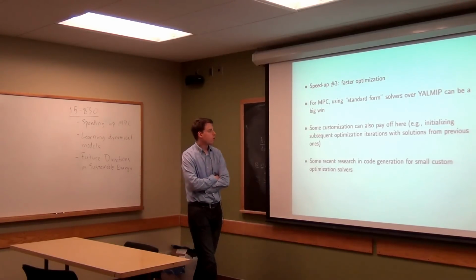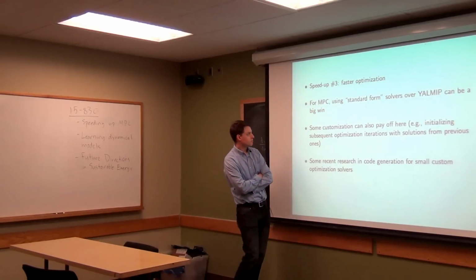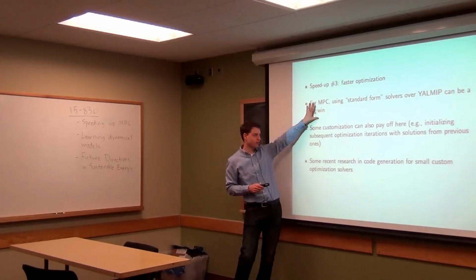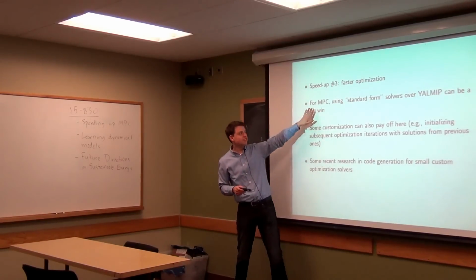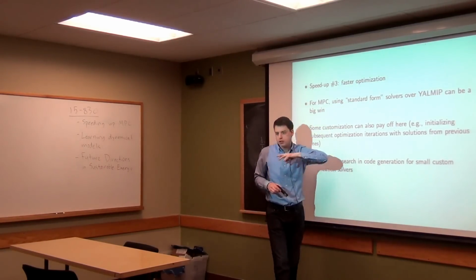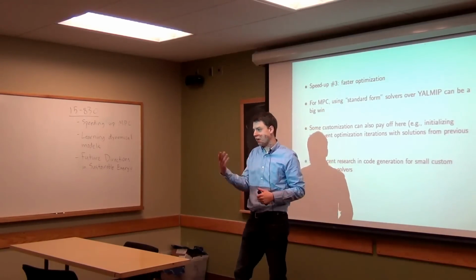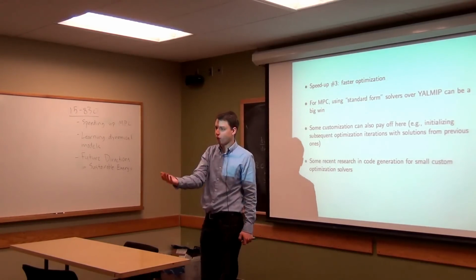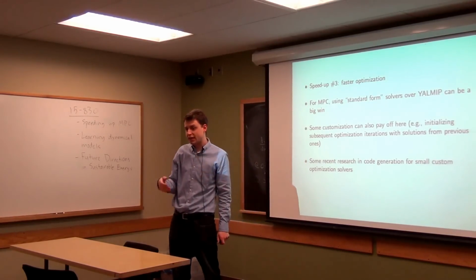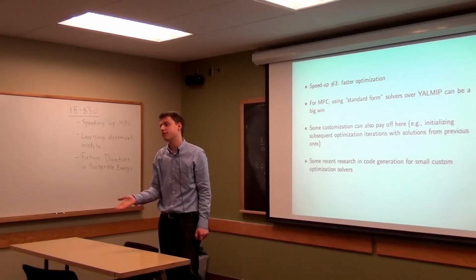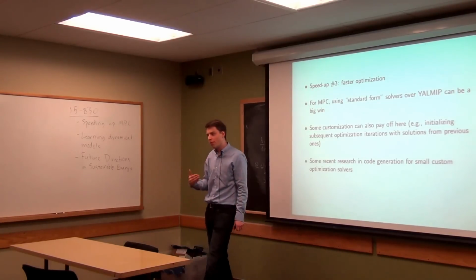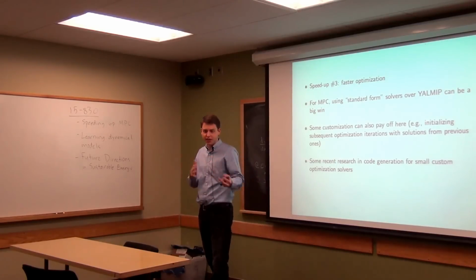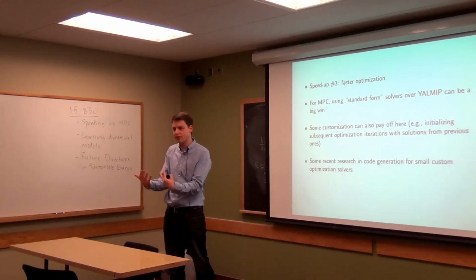There's a lot of work on, actually, before I mention that, I should say that fast optimization is a big win here. And for something like MPC, as mentioned before, using solvers that take as input a standard form problem, so just plugging in a standard form linear program or standard form quadratic program into something like CPLEX is typically going to be a lot faster than using YALMIP, because YALMIP has to run a lot of MATLAB code to parse these problems into standard form. That's what it's doing behind the scenes, right?